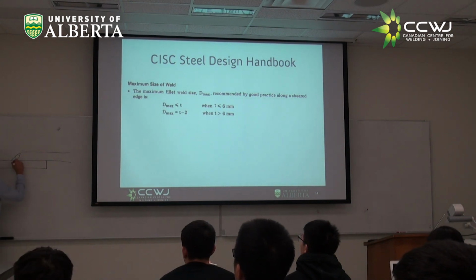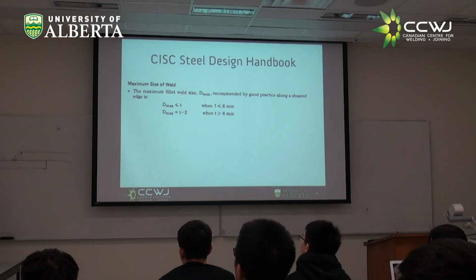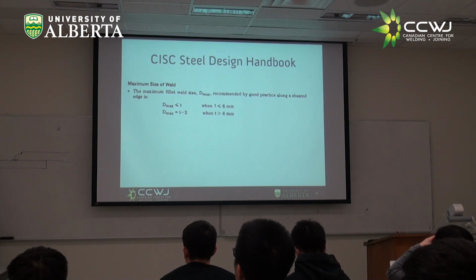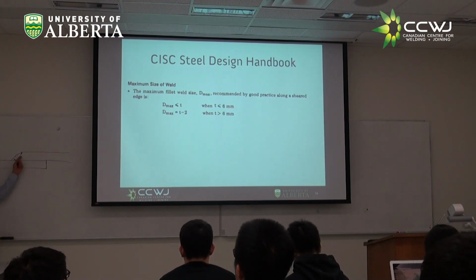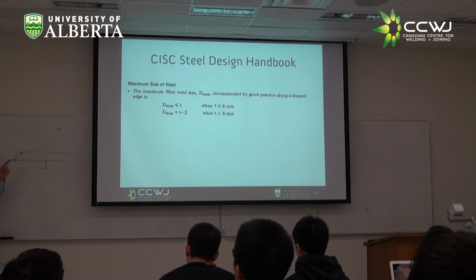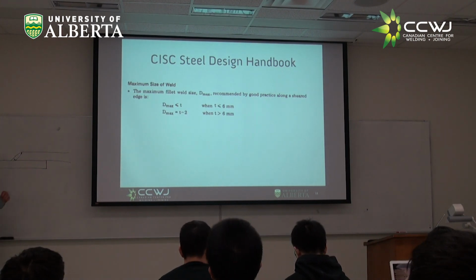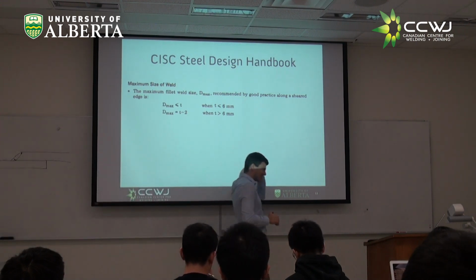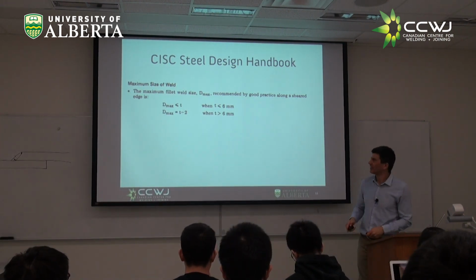If I were to do this weld here, there is no connection, right? I would have this tiny throat instead of the huge throat I meant to have. So the reason they said leave 2 millimeters is so you don't cheat. Now, people are doing mechanized welding, automated welding. In many cases, you don't need to do this, but it's still in the code. I think it's a pretty interesting thing, isn't it? Don't cheat, the anti-cheat code.